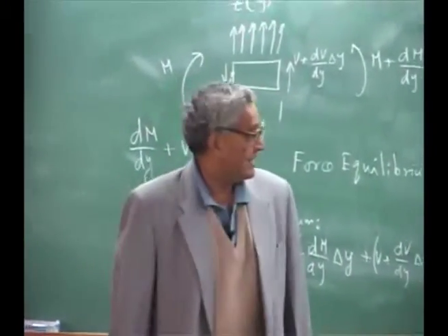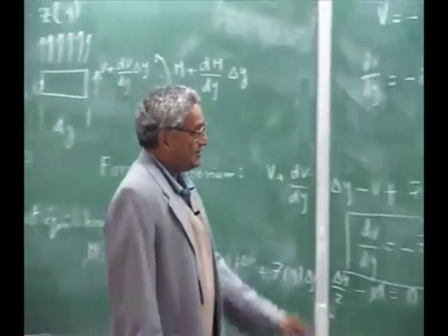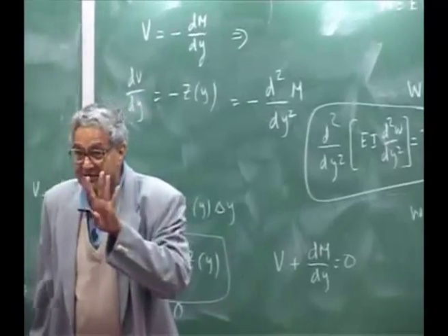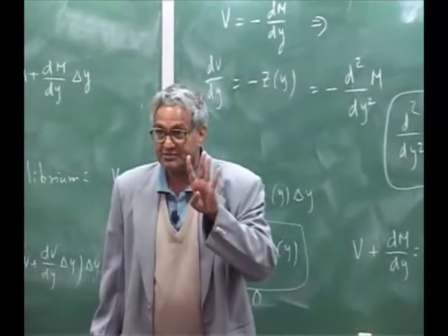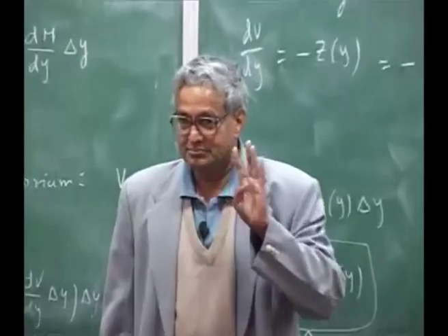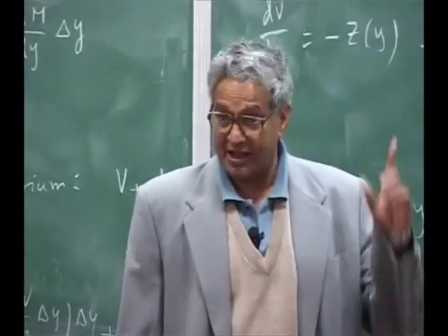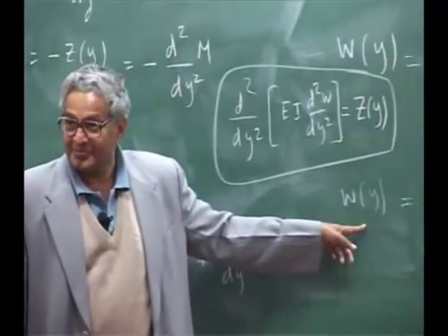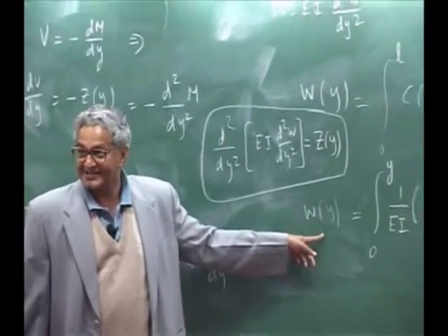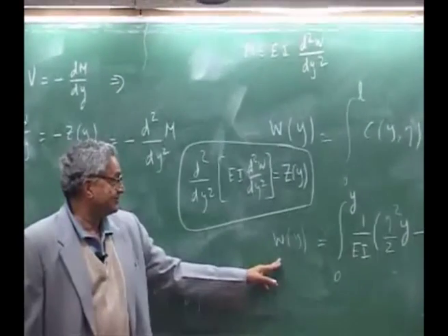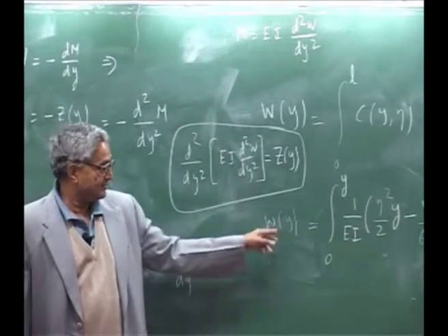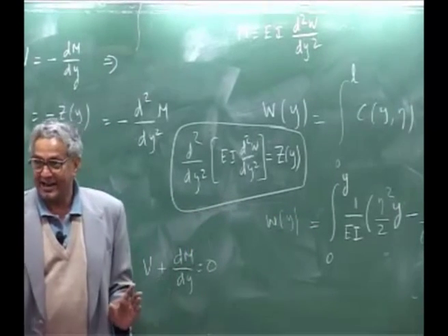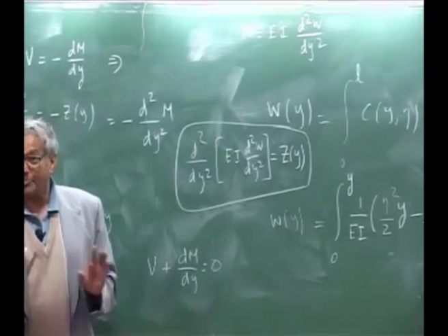Now, if you look at this, I have a differential equation. Please understand, this is a fourth order differential equation. I need 4 boundary conditions. I need to solve properly. Here, I have a solution which is W in terms of Z, the loading. Now this is what people call operators.